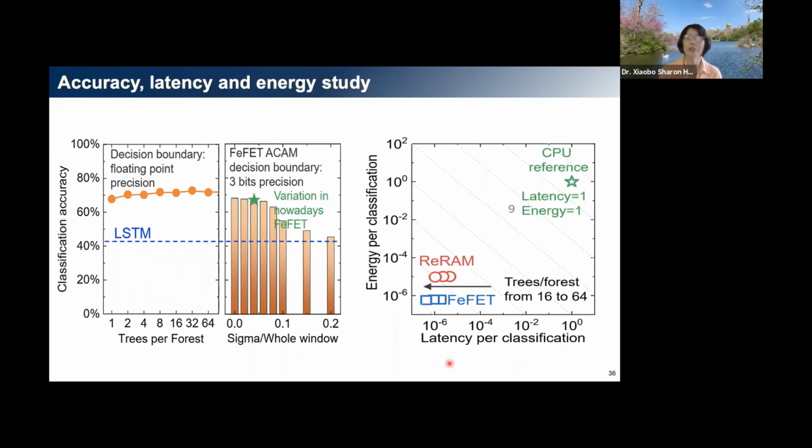Let's say I have these crossbars or AMs together with an FPGA type of framework, I think that should not be a problem. The only thing is we need all these new devices to be compatible with CMOS, which is true. RRAMs and FeFETs are both compatible with CMOS, so they can definitely be used in this coarse-grained manner, integrated with other types of reconfigurable fabrics based on MOS devices.